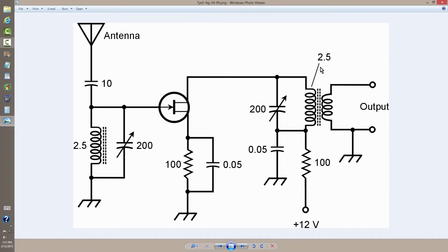The other thing is, where do you connect an oscilloscope, for example, to indicate resonance by peaking the amplitude of the wave that you see on the oscilloscope? Where would you connect it in these resonance circuits? Certainly not at the bottom of this one or the bottom of this one, because both of these points are at RF ground. This one through a bypass capacitor, and this one directly.